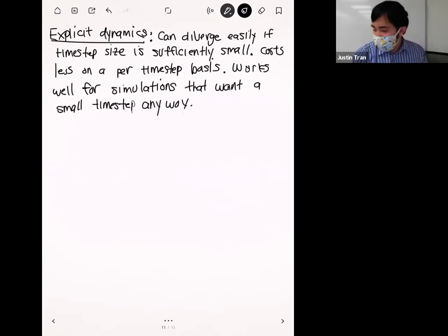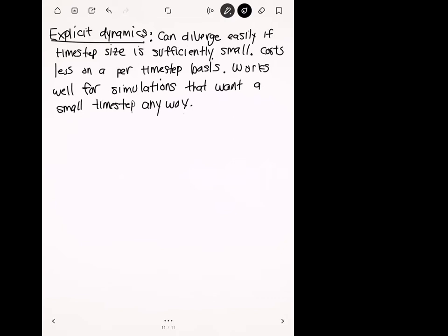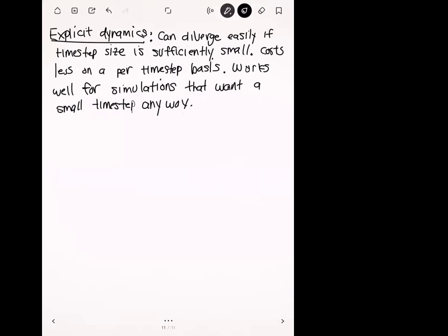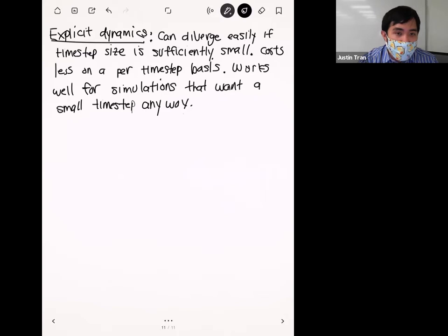Ashutosh, are you still there? Yes, sir. I have a problem of solver pivot warnings. That usually happens when your structure is under-constrained, so you probably need to add some more constraints. If you're having trouble with the displacement constraint, you can try adding a fixed constraint on that side. Give that a try, and then I think that should hopefully solve your issue.